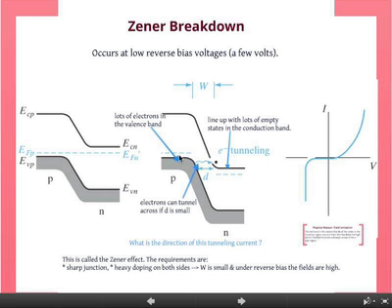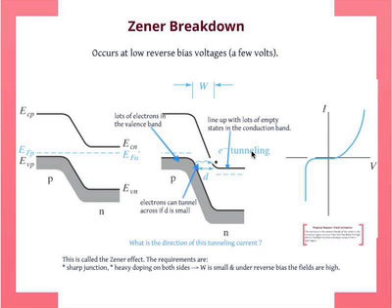So essentially what happens, you have lots of electrons in the valence band, which line up with lots of empty states in the conduction band. Electrons can tunnel across if this distance between them is small. Now, of course, if the electron tunnels this way from P to N, the current is the opposite way from N to P, which is the reverse bias current, right? Remember, the applied field is this way, the applied voltage is also in this direction, reverse bias, right? N type, P type, and this is the reverse bias current. Electrons go this way, current flows this way, reverse bias current.